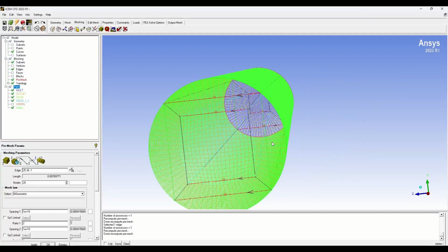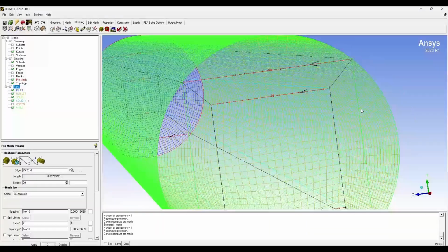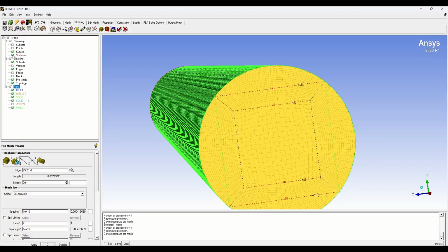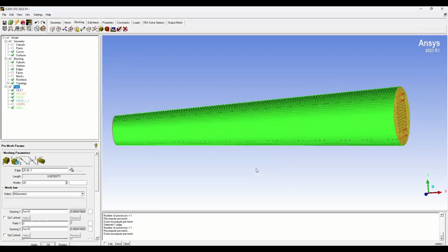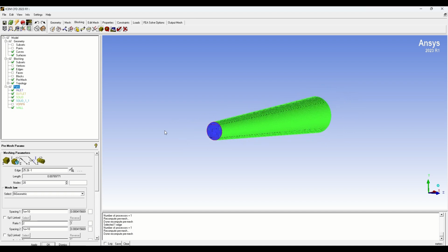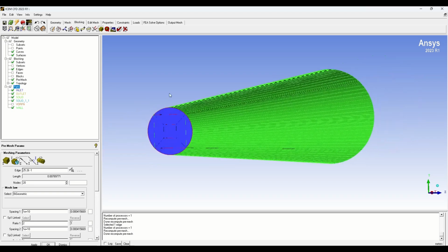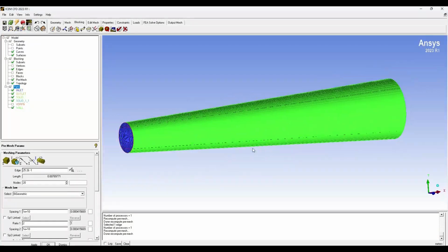You can see it in the front side, top side. This is an O grid structure. I'm just rotating the O grid structure, the square like in the center, and all the vertical lines, all inclined lines in the outer four sides. So this is the meshing after giving the surfaces as solid. So after giving surfaces, you can see the meshing has been done for the diffuser. So this video is useful